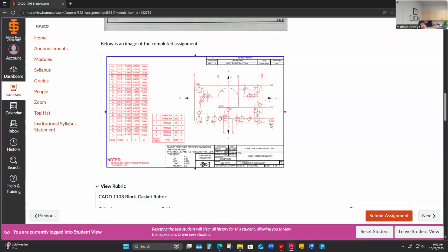Technically, I could go in and change this dimension style to orient the text into horizontal leading, but I think generally with ordinate dimensioning, even in the ASME standard, we're going to pull the text in the direction that the dimension can pull. Horizontal dimensions and then vertical dimensions, the text is rotating. So just something to watch. And these are subtle differences that we now pick up as drafters that someone else may not know about. It tells you that we're learning something, because now we can identify, well, there's some weirdness to this.